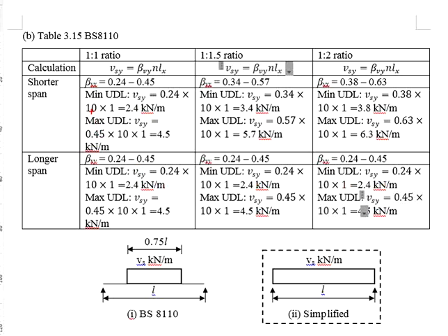Assuming the same magnitude of the UDL is applied throughout the entire beam span. Knowing now the UDL estimated in the British Standard is slightly more conservative than the U-line method, if we adopt the simplified method, the conservativeness increases, where this area is not considered to have any loading by the British Standard. Instead, we are considering it in the simplified method.